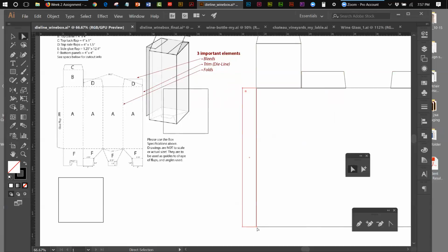That one is white, that one is white, not selected. That one is red with a little red dot there, indicating that that's the selected anchor point. And I again go to my 4 little arrows in the lower right corner of my keyboard, and I'm going to click on the down arrow about 12 times.